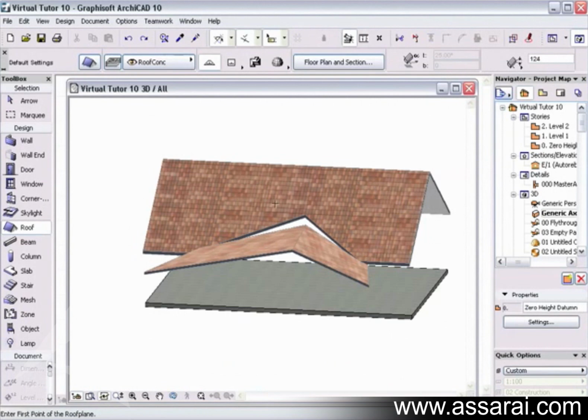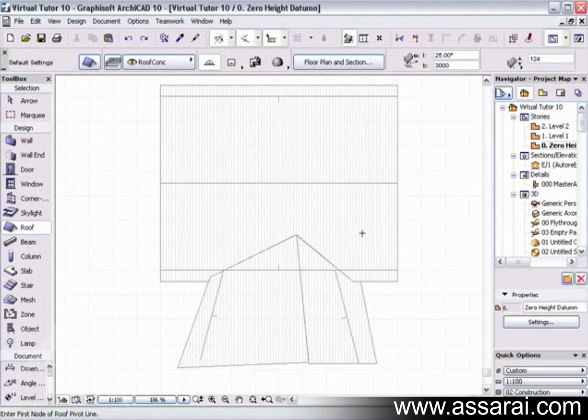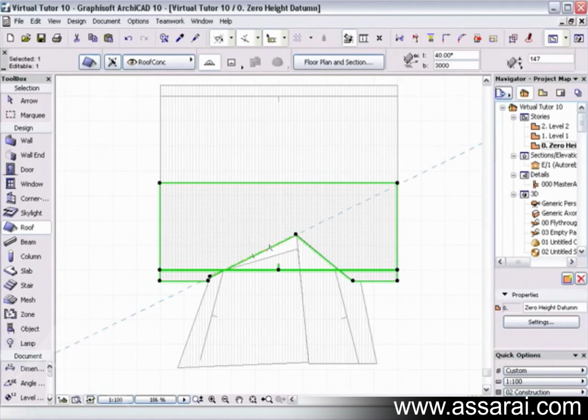we have to redraw the main roof still, so I'm going to close that once again. If I hold the Shift key down, select this roof, hold the Control or Apple key, wait for the Mercedes cursor, left mouse click, we can see the roof has come away, and same to this roof plane, left mouse click.